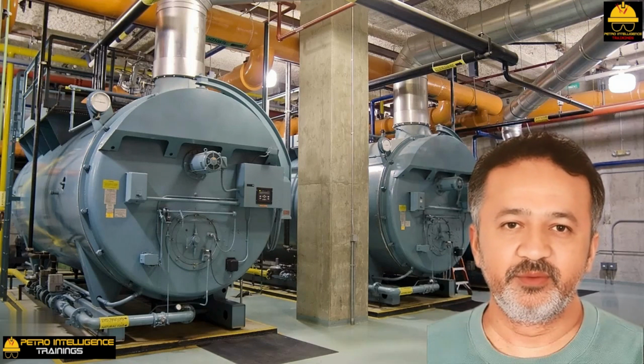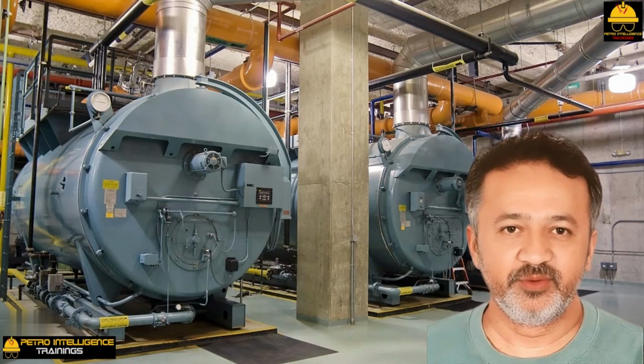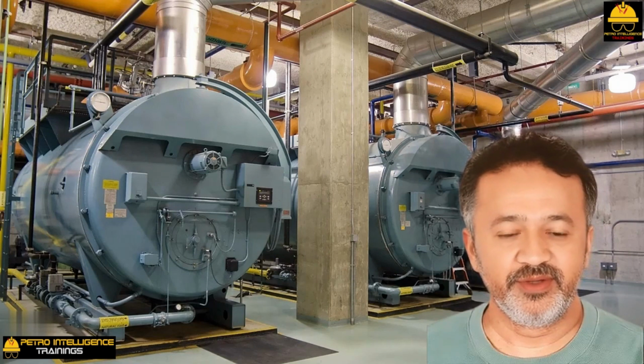Combustion air preheat in boilers, which are limited by excessive radiant section temperature or hot tubes, will always lose steam production capacity due to the air preheater.